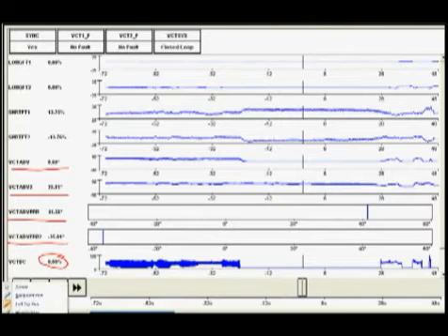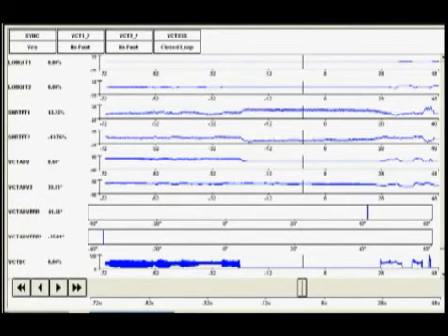The one thing that makes this pretty tricky is that Ford uses cam 2 for its cam crank synchronization. Since cam 2 is the cam that is in error by 35 degrees, the PCM is incorrectly marking where the cams are supposed to be and displaying an error for cam 1 as well. The cam that is not working properly at this moment is cam 2. Later on, after letting it get hotter and hotter, both cams will end up being retarded. The problem is that the PCM is relying on bad information about the correct position for the cam, and therefore producing an error for both cams. So now the question is, what would make a cam stick retarded, but then occasionally not do so?